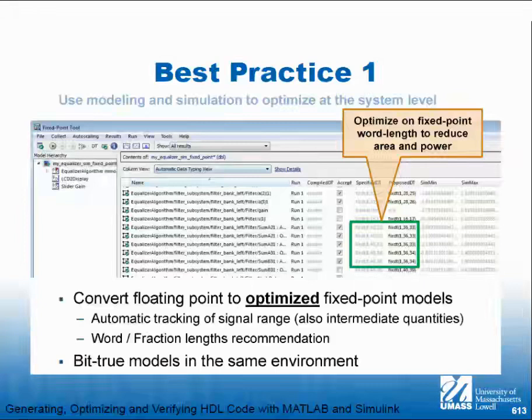It's a logic function that approximates math. So MATLAB does a really good job with that, but you have to tell it what to do. For example, it's hard to read up here, but on the slides, it looks good. You specifically state for every fixed point number how many bits it is, how many bits on the left-hand side of the decimal point, whether it's signed or not.